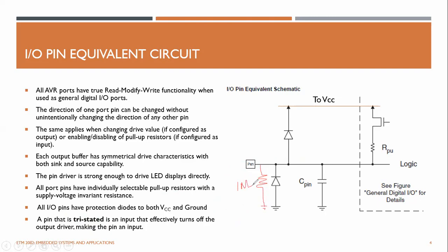It is not natural, but infinite is the ideal case, maybe 1 megaohm impedance, right? So if you have some kind of sensors or anything connected here, when you have high impedance, which means if a 5 volt signal comes here, only a very small current will flow through this resistor due to high impedance, and there won't be any drop in this voltage, right?